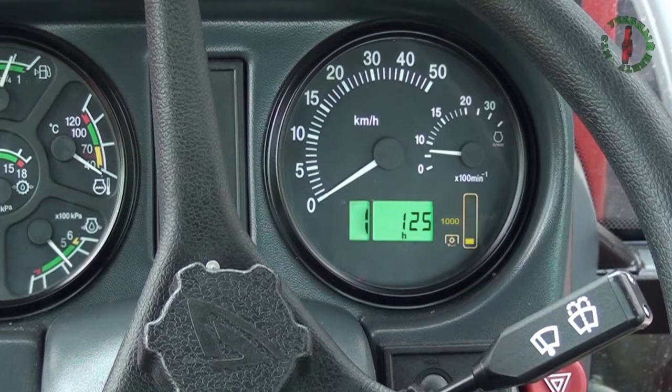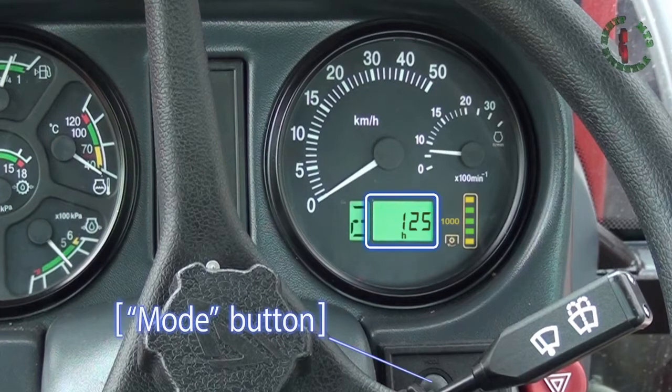The indicator 1000 revolutions per minute lights up, and all the segments from lower to upper begin to light up. The exact value of rear PTO speed can be seen on the multifunctional display. The multifunctional display is a liquid crystal display that shows different information. In the left field of the multifunctional indicator, the number of the current gear is shown. In the right field, by pressing the mode button, the following information can be shown.